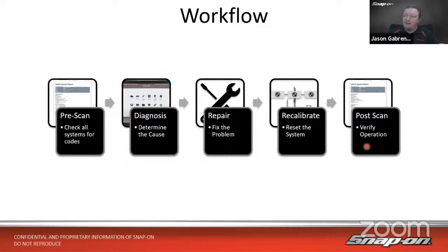And then after that, the final step before we hand it off to the customers, we'll want to verify the operation. We want to use that post scan to verify there are no codes left over, and also that all the readiness monitors are set as well. If all the readiness monitors are set and we have no codes, well, then the vehicle's in better shape than it was when it came in.